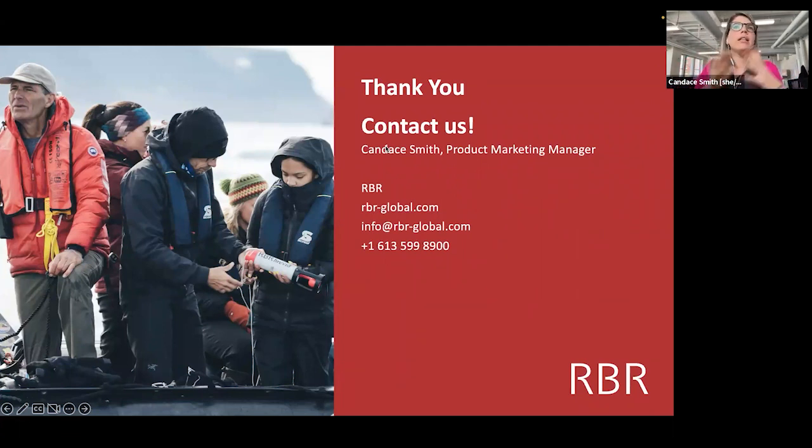So first of all, let's say you're on a typical, beautiful summer cruise. You're going out, the CTD is on the deck, and it's in the sunlight. Now the conductivity cell is like 25 degrees Celsius, and you put it in the water, and the surface water is like 20 degrees Celsius. So we recommend a little bit of a soak at the surface to get the thermal mass to equilibrate, because as you can see here, this is a piece of plastic, so it has to heat up or cool down. So if there's a big temperature differential, then you want to leave it in the water for the CTD to heat up or cool down.